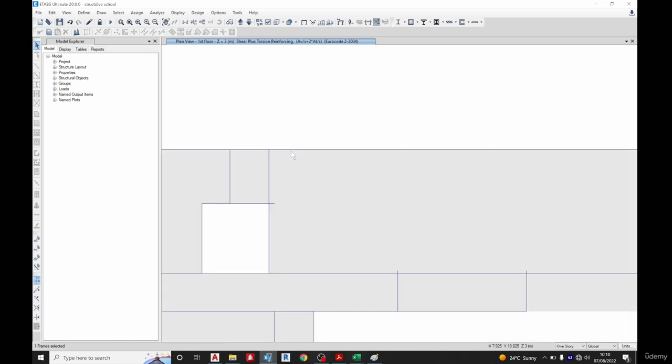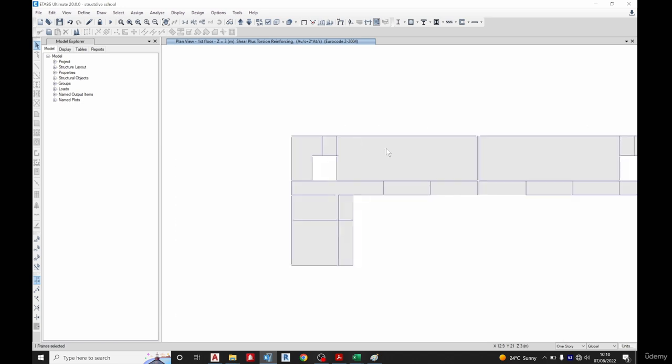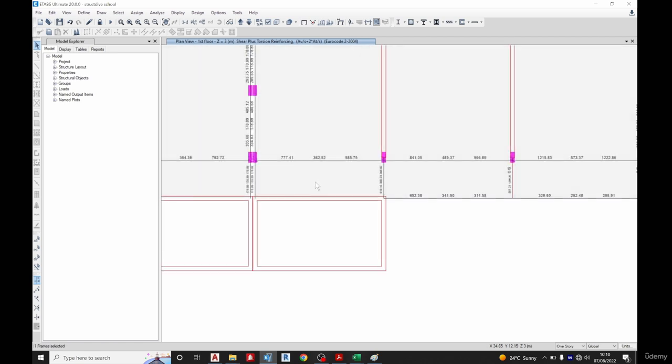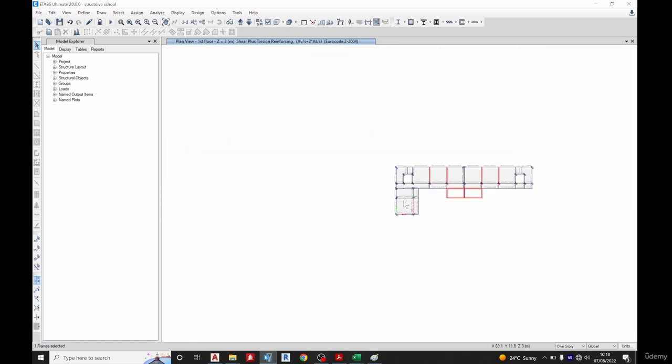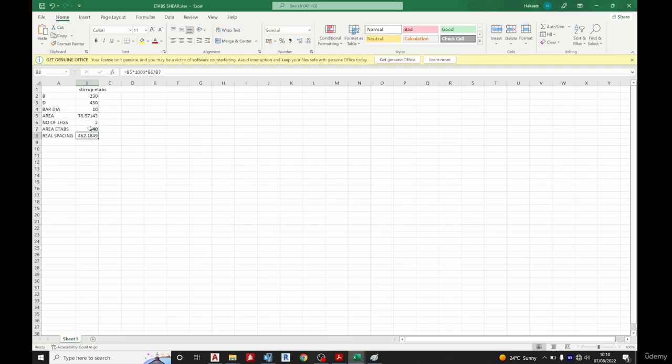But in our way, we are going to just select this and use a uniform link all through for this particular beam. So let's look for more beams with more critical loadings, more critical shear. So I think this one too has failed in shear. This one has a value of 1340. So ETABS is telling me, or I'm telling my draftsman, that I need 10 mm at 100 center to center for that particular place.